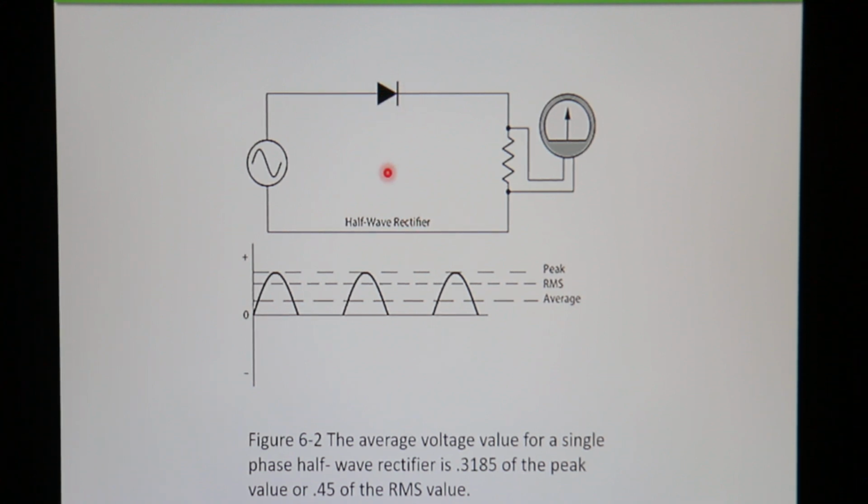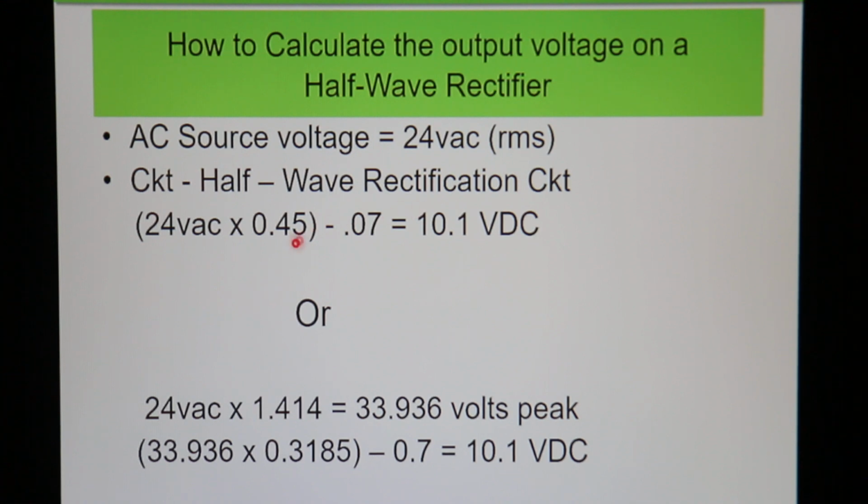So let's talk a little bit about diodes. I think you've already learned this in your labs. A germanium diode, to turn it on, we have to have that voltage at about 0.3 volts. For a silicon diode, that same turn on or biasing voltage is 0.7. So typically in our rectifier circuits, we're using silicon diodes. So that's why you see us say take that minus 0.7.